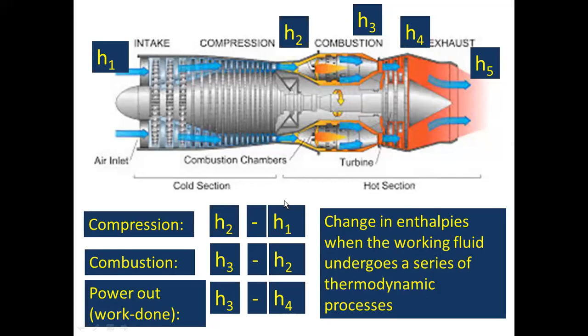Compression work, of course, is suction, intake plus compression. Once you take this flow in and compress, the enthalpy rises from H1 to H2. So compression work is H2 minus H1. In combustion, again, because it's a flow through, later you will know that combustion is H3 minus H2.